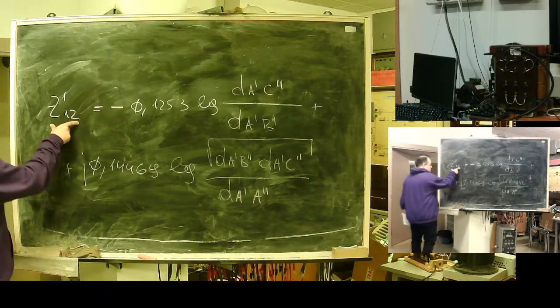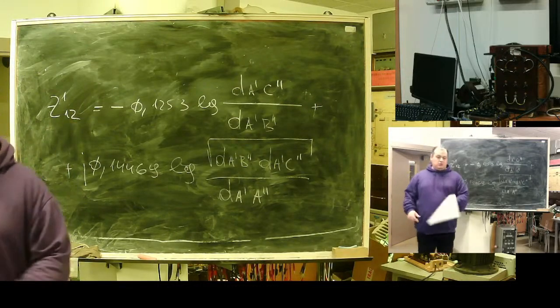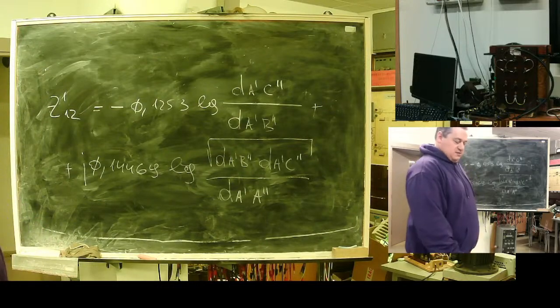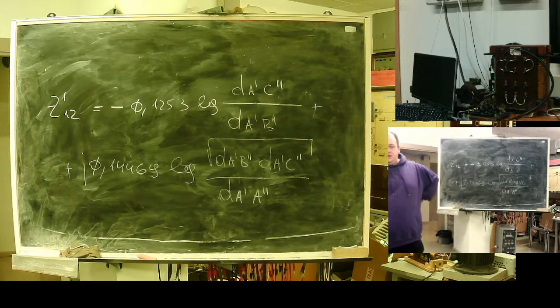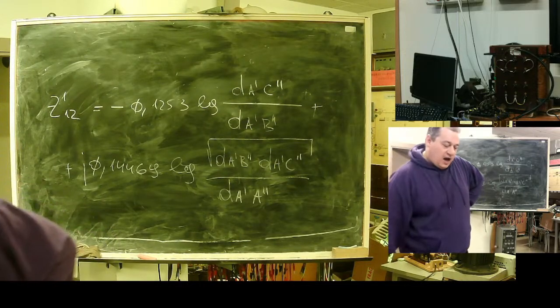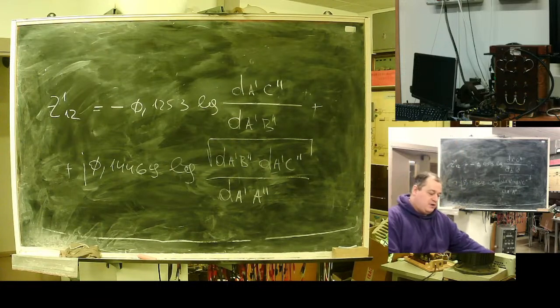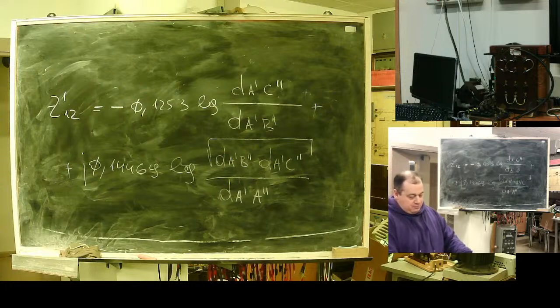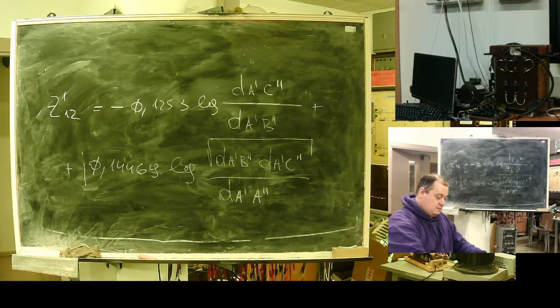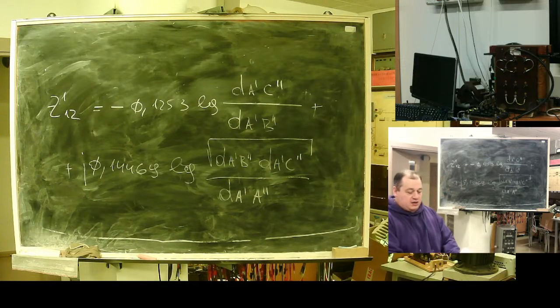This term usually is less than 1/3 of the direct sequence self-resistance, but it's not zero. And it's a source of quite a mystical thing: current in the disconnected line. You can have a disconnected line, but you see an induced current in it from the neighboring line or lines.